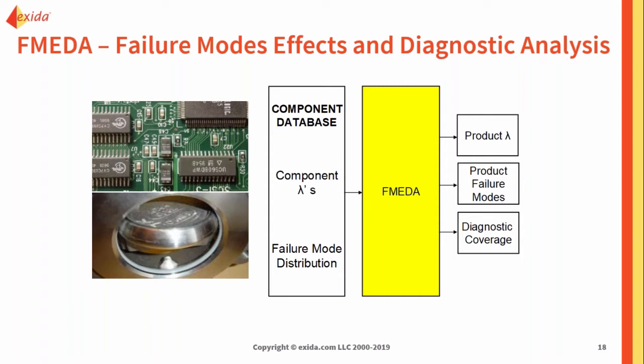So we would do an FMEDA on a manufacturer's ball valve or pressure transmitter or sensors, down to the manufacturer's series, make, and model. It's going to be based on the design and the parts that are used, any design margins.